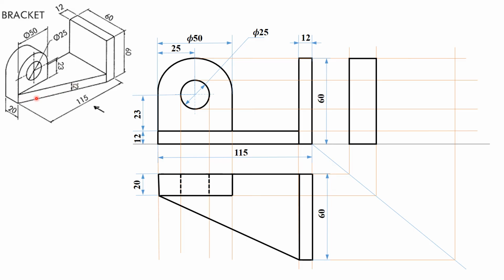Since it is inclined, the surface will be visible in your front view as well as in your side view, but only to a limited length, which I can take from this point. Before that, do the hole view also here. Here also this hole will be viewed as a hidden one, which runs through this length. The length is 20, which I have taken from here. And the surface. With this, things come to an end.